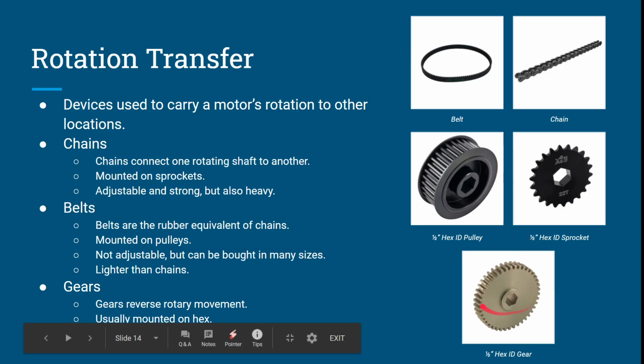Because if you have a bigger gear going in here, and that goes to a smaller gear, for the same surface velocity, it's going to have a different number of rotations per minute, different RPMs, which is going to give you a reduction. So if you're spinning this with a smaller one, this one's going to move slower than the smaller one. So yeah.